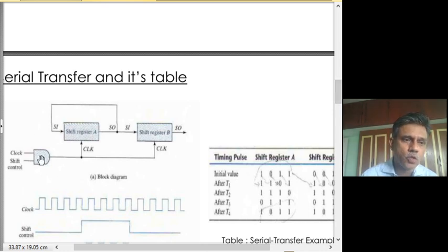and for that we use this simple circuitry wherein the clock is being enabled or disabled using a shift control. We already mentioned that this is not a good way of designing or working with a clock, or introducing logic in the clock circuitry is not desirable, but it is okay if the circuit is simple and race condition will not occur.